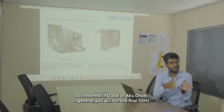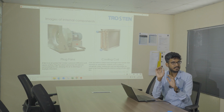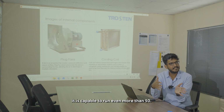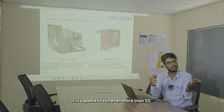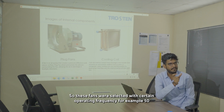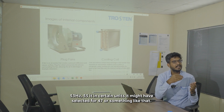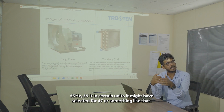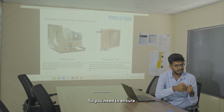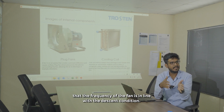So normally, in Dubai or Abu Dhabi, in the UAE in general, you will run the fan at 50 Hz. But in this project, these plug fans are capable of running even more than 50 hertz. So these fans were selected with a certain operating frequency, for example 50 hertz, 53 hertz, 55 hertz. In certain units, it might have been selected for 47 hertz, something like that also. You understand, right? So you need to ensure that the frequency of the fan is in line with the design